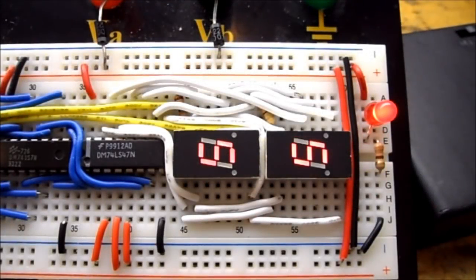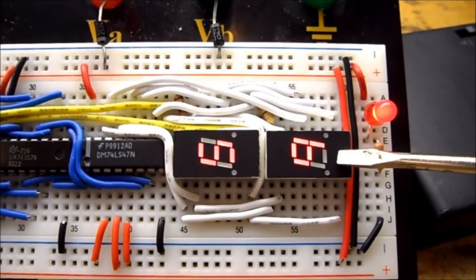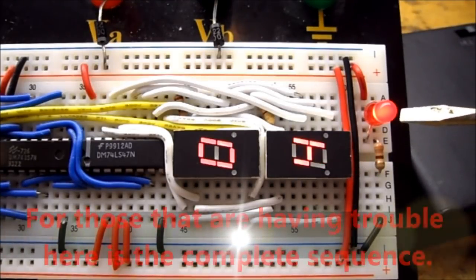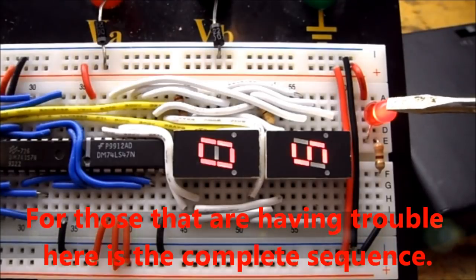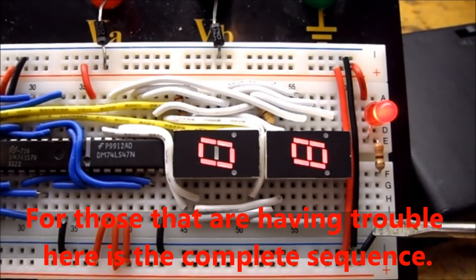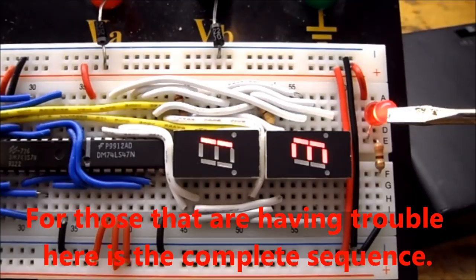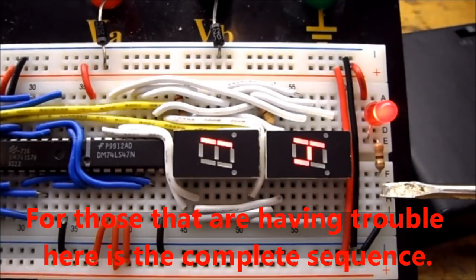So this is a close-up of my count sequence. You can see the lower digit is my ones digit, and it just reached 59 and went back to 0, 0. I also have a power on indicator just to indicate the power is getting to my breadboard, because if after hooking up this circuit nothing works, we need to know if power is getting to our trainer.